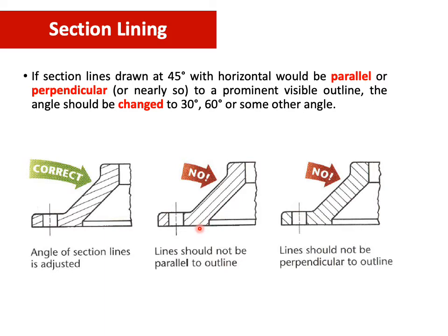So the lines should not be parallel, and also cannot be perpendicular to your object. You need to adjust your section lines to 30 or 60 or more, it depends on you, but don't try to do perpendicular lines. I prefer you change to 30 or 60.